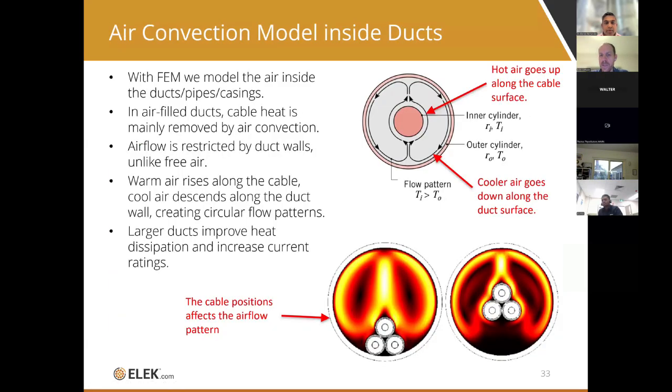Air convection model inside ducts. This is very important. If you're modeling ducts, you have to accurately model the convection inside the duct. It actually depends on the cable position and the arrangement of the cables in the ducts. Now, this is not captured in IEC calcs, but it is calculated in FEM. So FEM is very flexible.